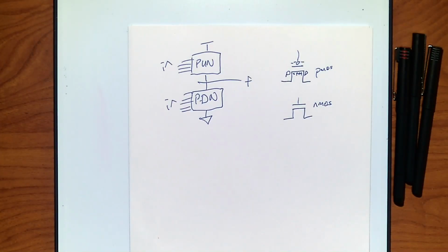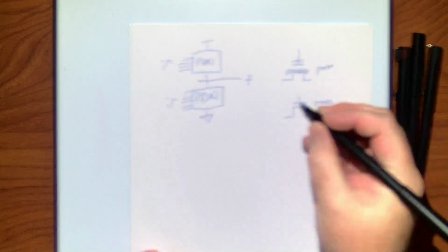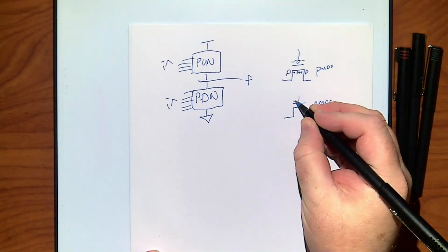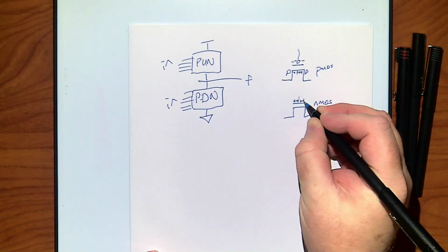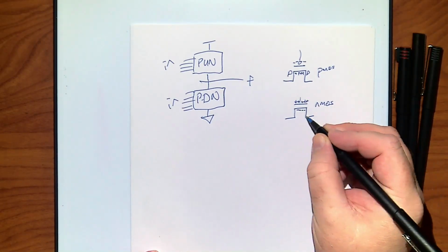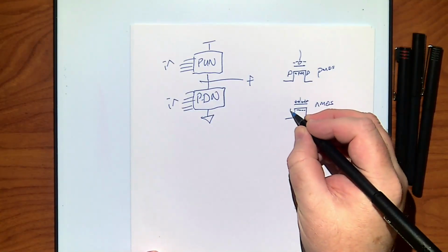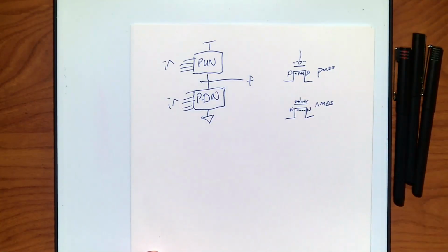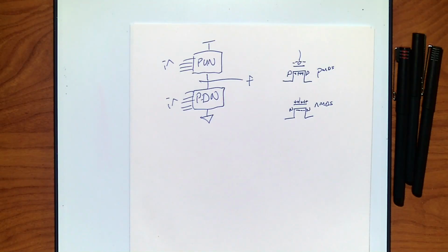So now they're connected. Otherwise, I've got N material in between, and I have that diode front to back, and I can't get any flow. The same idea, the opposite, happens here. I get a bunch of pluses up here, so I can make an N-type channel, all electrons down here because these two sides are N material. So I want a channel made that does this.